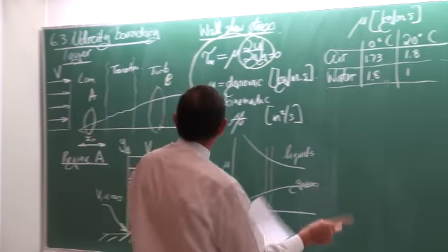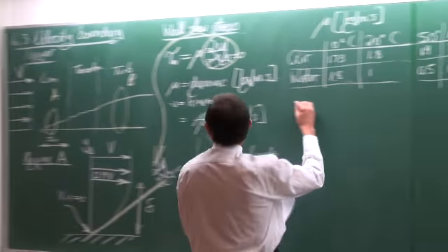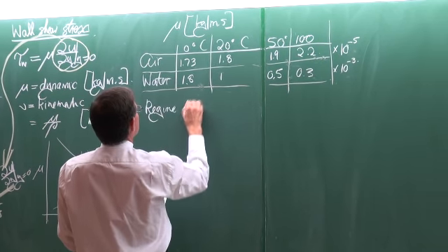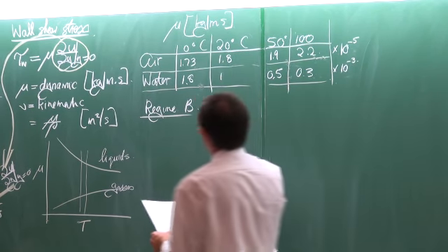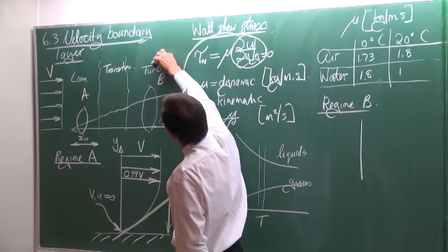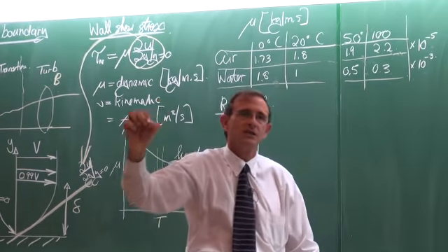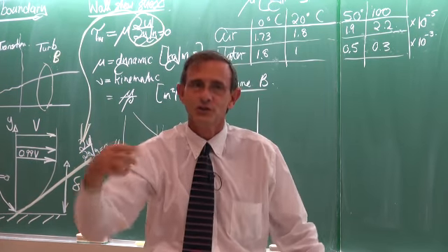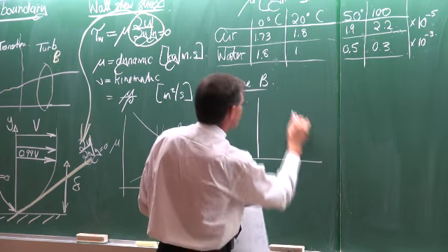Right. So that was now the velocity distribution in the laminar flow regime. Let's look at it in regime B, the turbulent flow regime. How does it look there? The turbulent flow regime, again, if we start taking measurements far away from the wall, come closer and closer and closer, and again it is with one of those magic instruments that we haven't developed yet, where we can go and measure without disturbing the flow, then the velocity distribution would typically look like this.